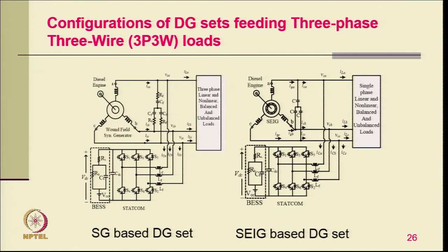So, in such sites where you have a dynamic load, maybe a kind of water pumping or other motor loads, where you want to use the DG set as an emergency supply, the battery really helps us for power leveling on the load side as well as on the generator side. That can be used in a conventional synchronous generator also, but here of course, you have voltage regulation typically only what you have to do.